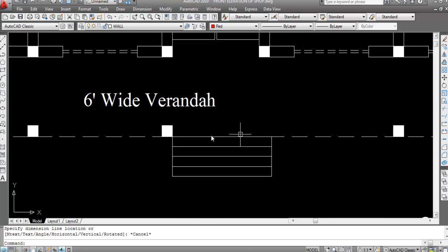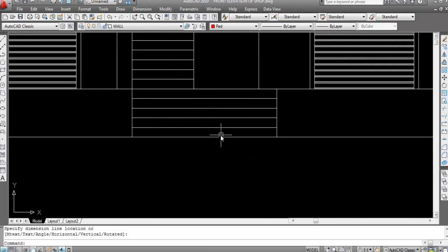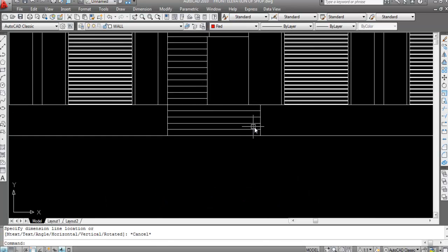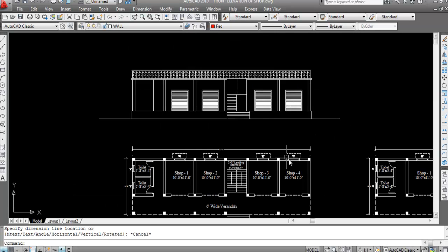Now here this is ground level to plinth level, 4 numbers of treads, 9-inch treads. Okay. Now here we need to create 5 numbers of 6-inch risers, 1, 2, 3, 4, 5. Okay. And this is 6-inch. Alright. Hope you understand how to create front elevation and how to create staircase on front elevation.